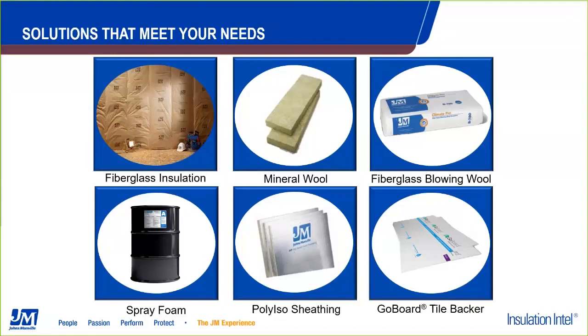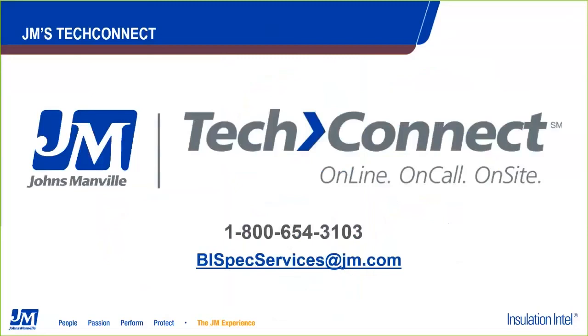Polyiso sheathing has been around for a while. This can be above grade and even below grade. It can function as either simply a continuous insulation or a weather barrier component. And on the lower right here, we've got a tile backer board, which is basically a polyiso board that has structural characteristics in the facers that make it an excellent waterproof backer board, as well as an exterior sheathing board for certain applications. So I wanted to take the time to go through those, and I'll hand it back over to Kim to take us through to the questions.